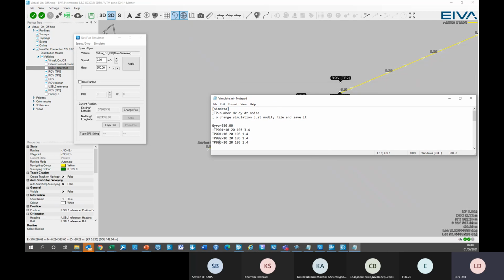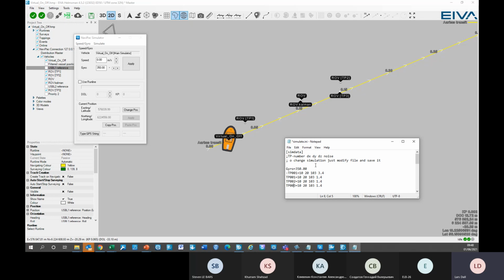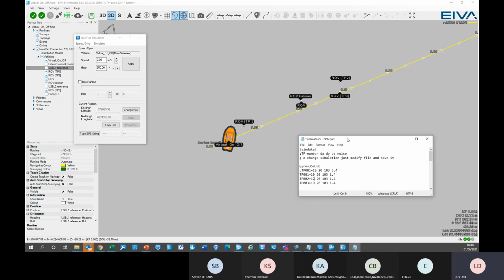Now, you remember the offsets that we were using? If we say that TP1 has X offset of 10, then TP2 has X offset of 12. Notice that TP1 X value was -1, TP2 X offset was +1, so the difference is 2. So if I do it like this, then they will match approximately. The Y value is the same, and the depth is also approximately the same.